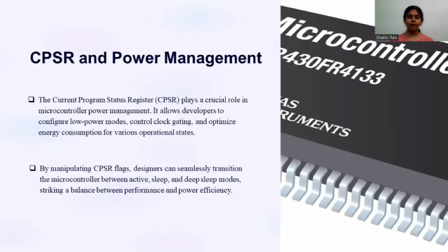CPSR and power management. The CPSR plays a crucial role in microcontroller power management. It allows developers to configure low power modes, control clock gating, and optimize energy consumption for various operational states. By manipulating CPSR flags, designers can seamlessly transition the microcontroller between active, sleep, and deep sleep modes, striking a balance between performance and power efficiency.